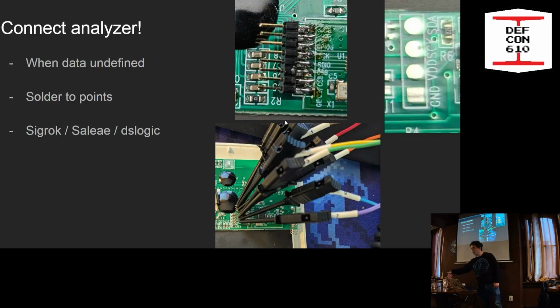I have the analyzer hooked up here, which you can look up after, but it basically looks like this bottom picture. Every single data line has a little gripper attached to it, and you need a ground point, so you can either take that from the battery connector or from the plug itself, because it needs to know the voltage difference between ground and whatever signal you get.